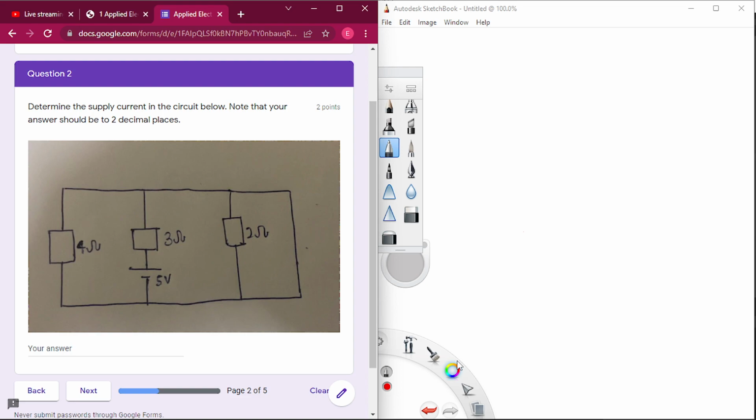When current flows from this battery till this end, there are one, two, three branches for current to flow through. And I said current uses the path of least resistance. When current should use this path, there's a resistance. When current uses this path, there's a resistance. But if current should use this path, there's no resistance. And we say once there's a path of zero resistance, all the current entering uses that path. Okay? Wouldn't branch here, wouldn't branch here, but then will all flow through the side.